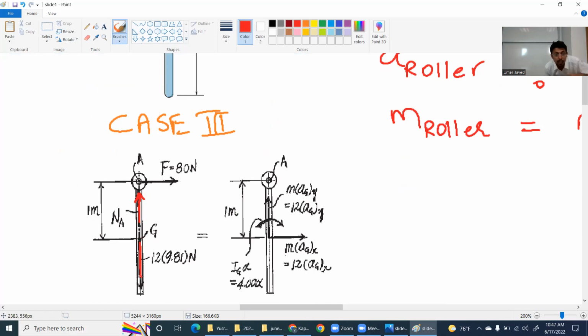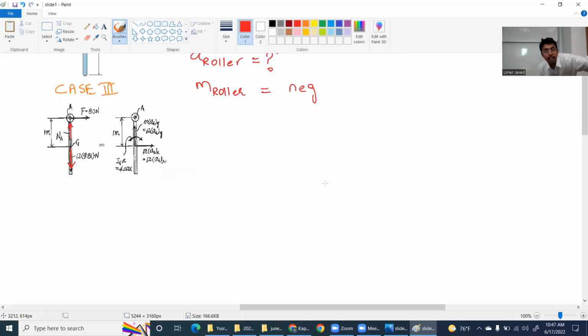So students are getting confused, so I will make an arrow like this. Why is there an equal to sign here? Summation of forces is equal to MA. So the author has made a kinetics diagram and just multiplied this with M. I hope it's clear. This is how the author does it. I usually in the classes make the free body diagram, and then I also make a kinetics diagram in which I show the accelerations. But if you even do this in exam for every problem, it's so cool, right? Because you are putting an equal to sign and you are just multiplying the accelerations with M and the angular accelerations with I.